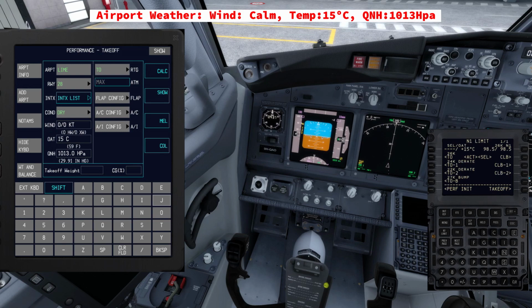By selecting the derated takeoff thrust, we are telling the software: I want you to calculate how much weight I can carry with the maximum takeoff thrust, the weight that I can carry with 24,000 pounds of thrust, and the takeoff weight that I can have using 22,000 pounds of thrust from the engine.